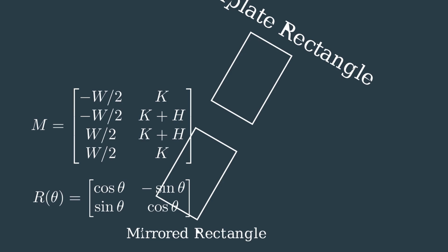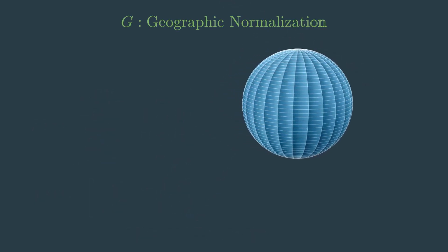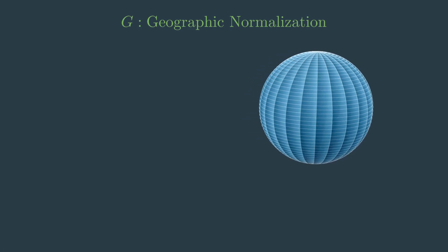Mirrors them? How? Mathematically, it's super simple. It just multiplies the rotated coordinates by -1. That's the same as a 180-degree rotation. It does this before converting back to real-world coordinates. This guarantees the second rectangle is perfectly symmetrical to the first one, right across the street center line. Wow, okay, that is clever. It's like a digital mirror image.